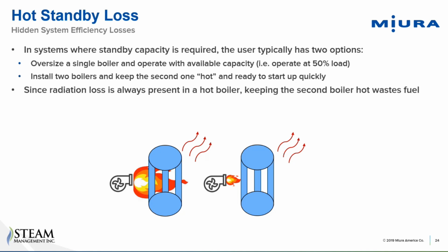Usually I'll see a boiler operating in really low fire just for a minute to warm it up, and then it has some set pressure that as the temperature drops, the pressure drops a little bit, and when it reaches some pressure, it'll come on again. But it can be done with warm up coils, which is running a little bit of steam through that boiler to heat it up. It can be keeping the boiler in a very, very low fire, if it's got a high turn down. So there's a few different ways to do it depending on the boiler type and the system needs. Yeah, cool. Thanks.